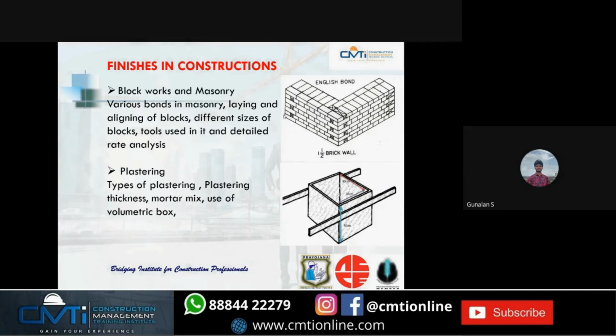The various tools used here are plumb bob, right angle, etc. So plastering work. This is a volumetric box. A 50 kg cement bag is put in this, and it should be leveled. The volume of this is 0.35 cubic meter. So a 50 kg cement bag is 0.35 cubic meter of quantity.